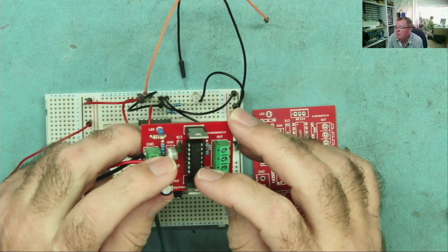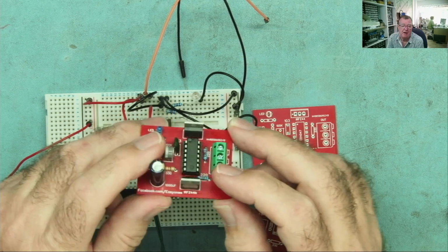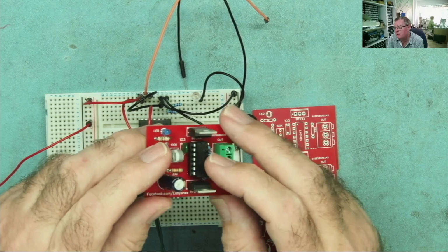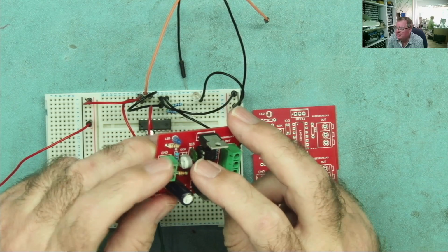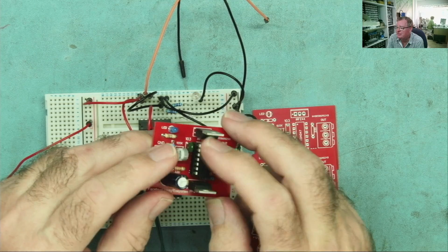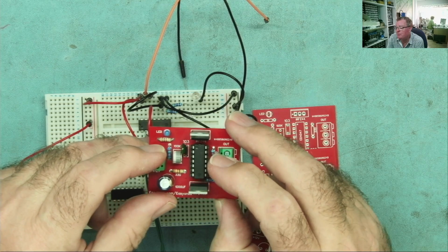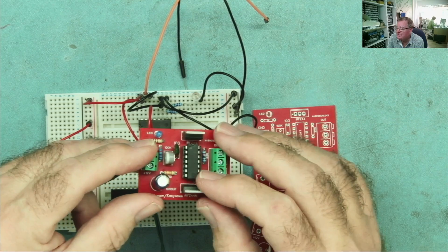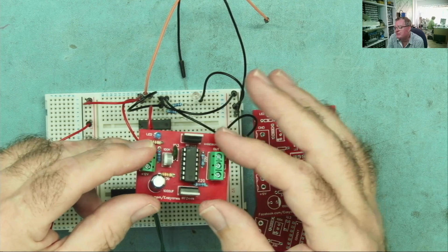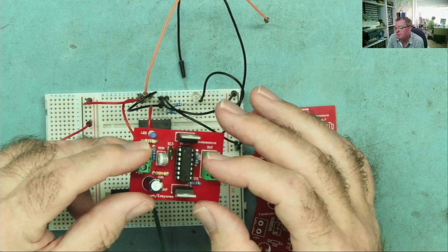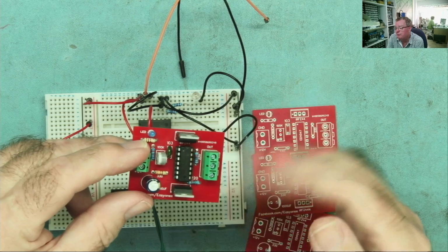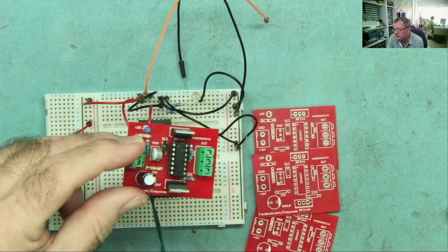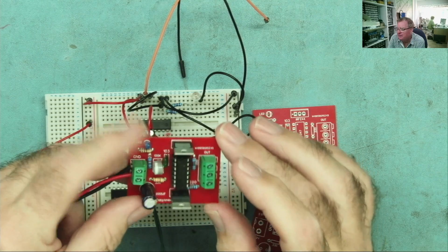The way this chip works, it is a multi-vibrator. That's what this circuit is called. I would call it an oscillator. There must be some historic reason why it's called multi-vibrator. Okay, but this capacitor and this variable resistor set the frequency, and on pin 13 we can see a square wave at the frequency set by these. Pins 10 and 11 actually come through a frequency divider, so these run at half the frequency of the main oscillator output on 13, and they switch on and off alternately. So first this one is on, this one is off, then this one should go on and this one is off, and vice versa. And this is what's not happening.